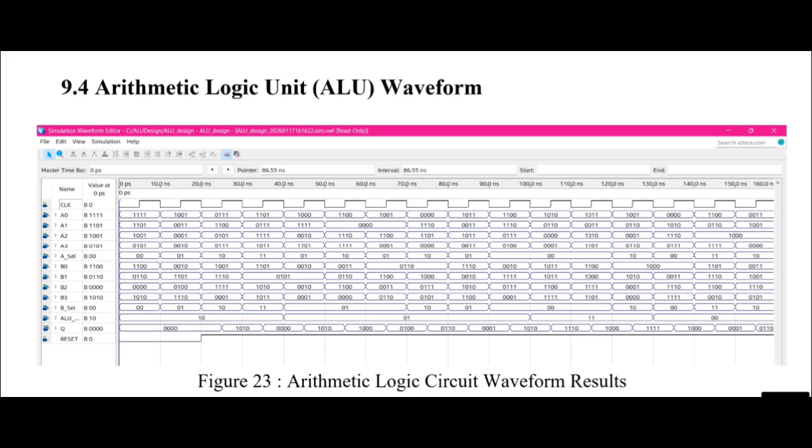The outputs from the multiplexer along with the ALU select signal are connected to the adder subtractor block. The clock and reset signal along with the 4-bit outputs from the adder subtractor serve as input to the register. On each clock positive edge, the register captures the input data and outputs it as the final ALU output.